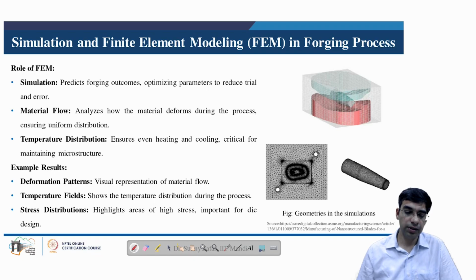Stress distributions highlight the areas of high stress, important for die design because it is the die which is used multiple times, so the die has to be designed to withstand the stress distribution over a cycle of manufacturing several components. So we can see some aspects of finite element modeling being used, where we can see the meshing being conducted on the right hand side to generate the mesh on which the finite element modeling will be conducted.